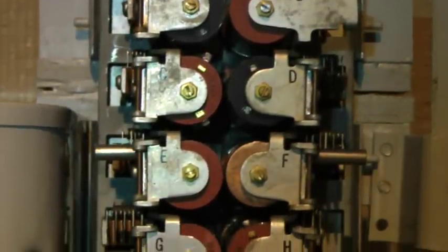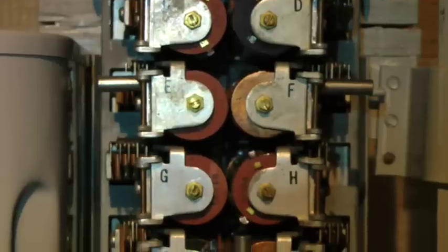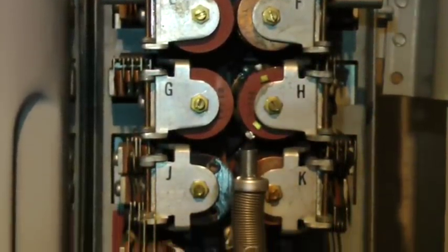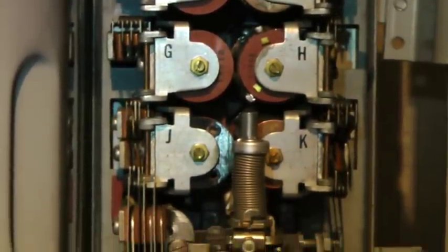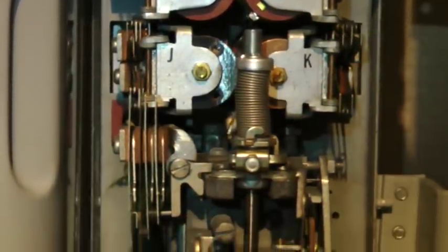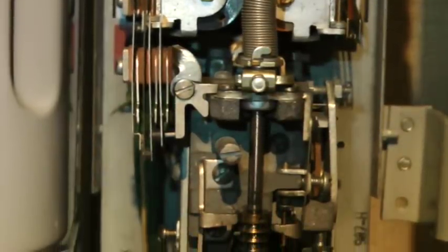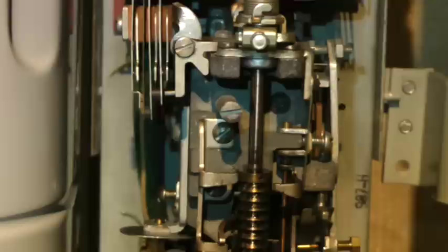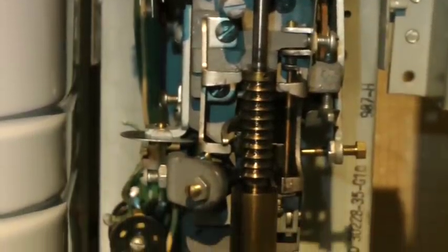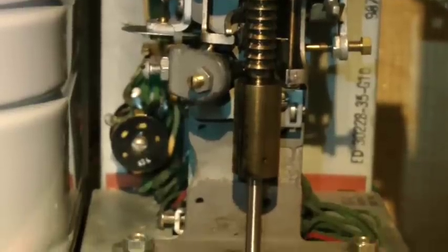I'm going to scan up and down the connector to give you an idea of its component makeup while I comment on some pertinent aspects of connectors in general. There are three main categories of connectors. The first category concerns the call type, local or toll. Some connectors handle local calls only, some handle toll calls only, and others handle a combination of both local and toll calls. This particular connector is a combination local and toll connector.